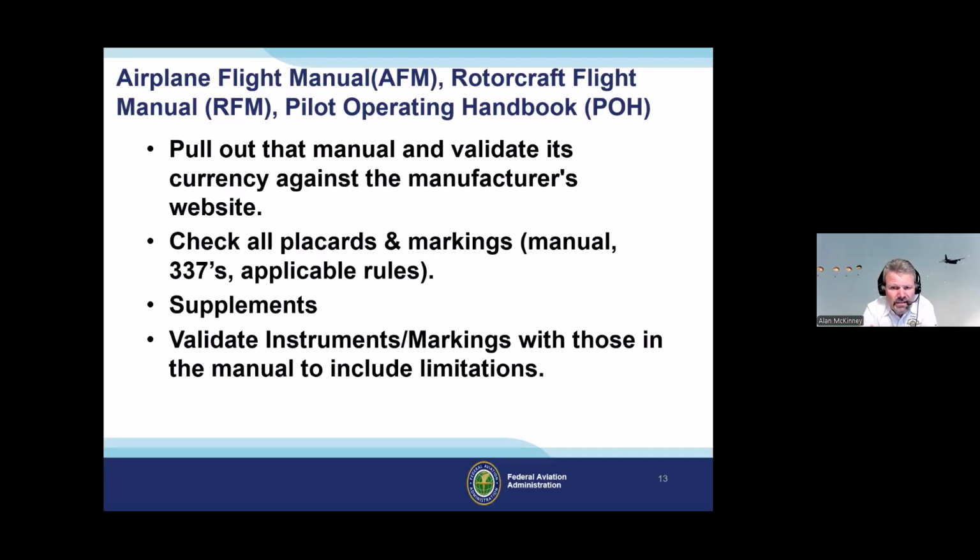So I was assigned as the inspector, and I literally took the RFM, rotorcraft flight manual, with all the supplements for any of the alterations, and I went and sat in the aircraft and went gauge by gauge, instrument by instrument, and I made sure that the picture in the flight manual under the limitations matched what the gauge said. And guess what? I found a turbine out temp gauge that was wrong.